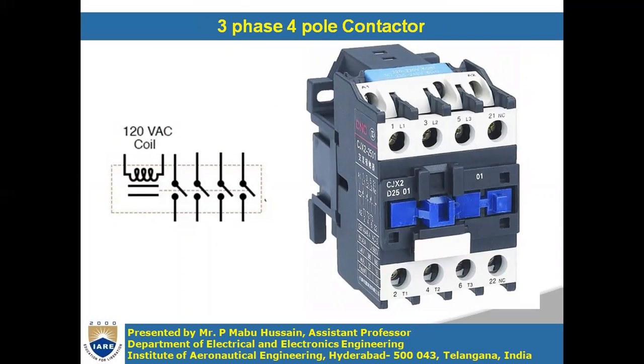For this purpose, we will use the three-phase 4-pole contactor. This is the picture of a three-phase 4-pole contactor. It has 4 poles and one coil inside. Whenever this coil gets 120 or 220 volts AC, all 4 poles will be closed. This is the operation of the contactor. The coil supply depends upon the manufacturer.